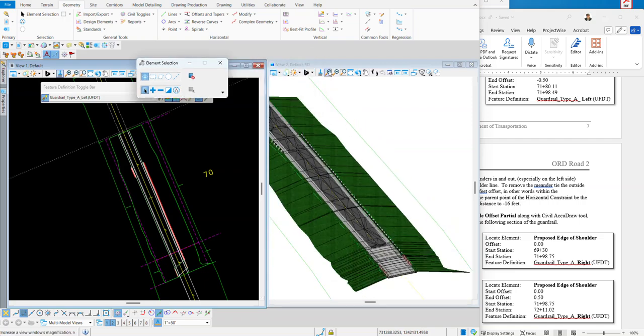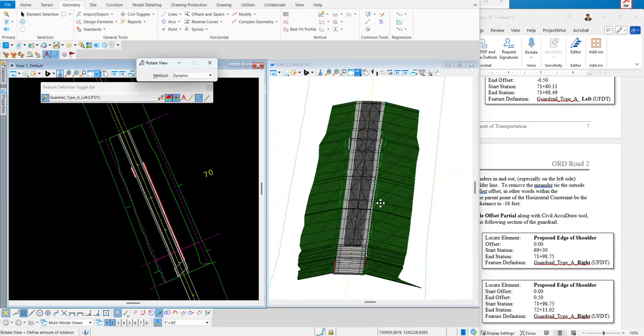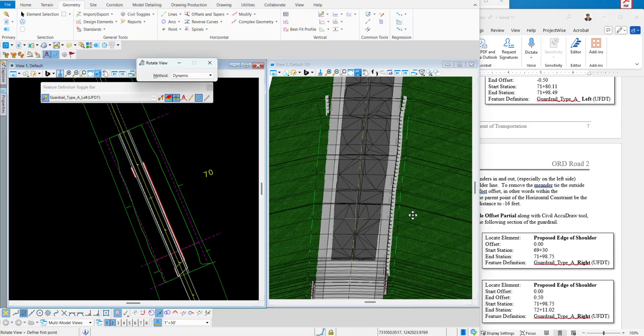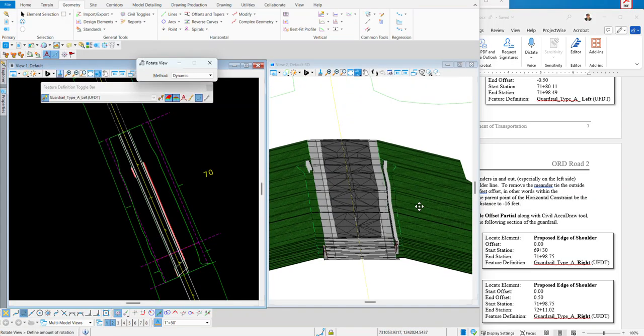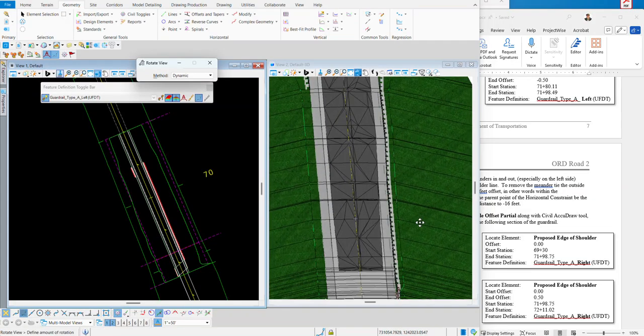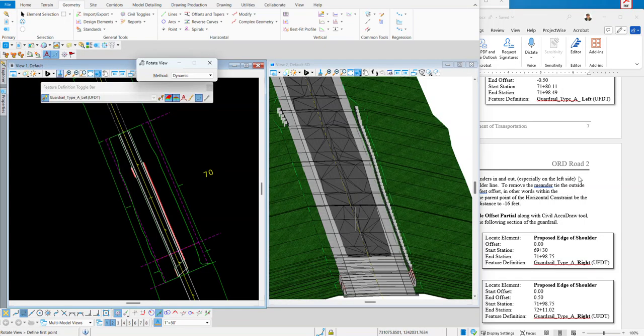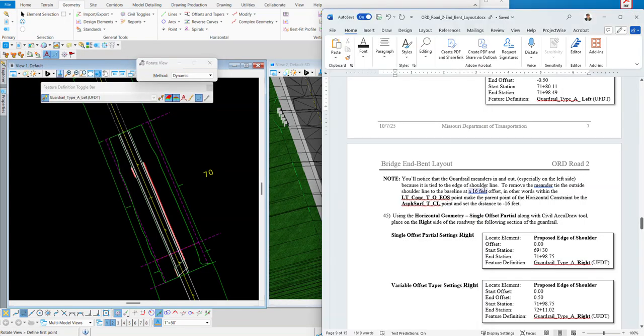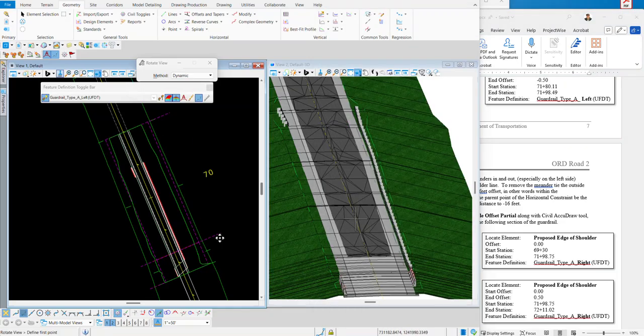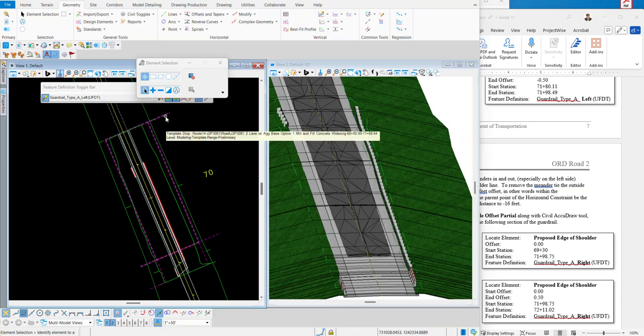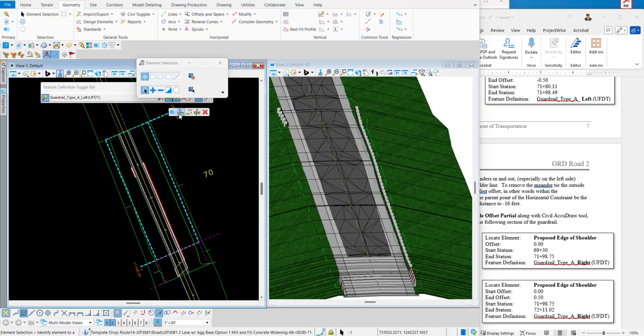The way you see this is if we do diamond rotation, you can kind of see what's going on here. It's just kind of going a little bit in and out. So it's doing that so-called meandering thing. Okay, so it's saying to fix that, we need to go into our template drop. This one here. Edit template.